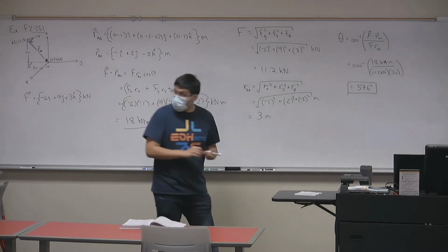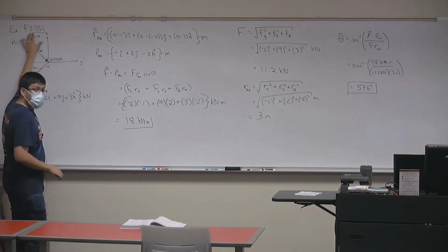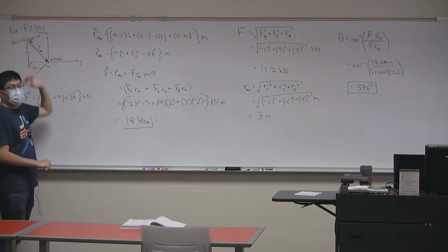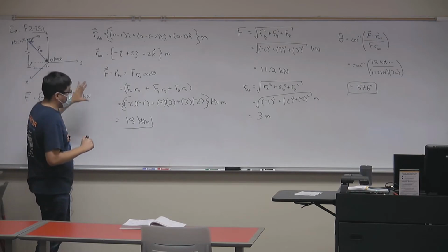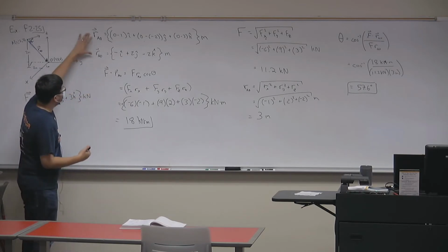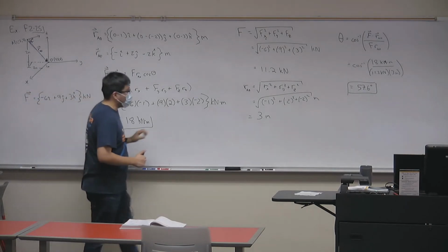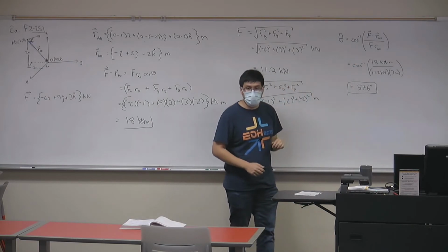So we found the angle between my force vector and my imaginary line, given 2 points and the force vector itself. That's good, because at least you knew that we had to convert that line into a vector by using the position vector. And then you knew how to apply the equation for the dot product in order to find that angle.